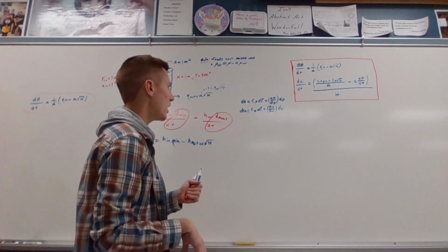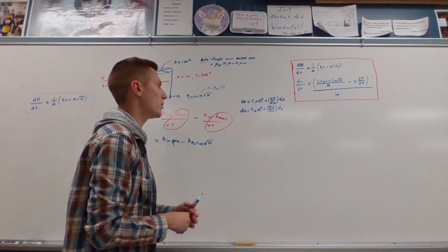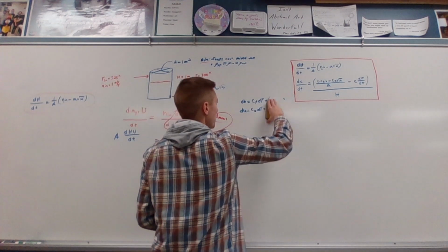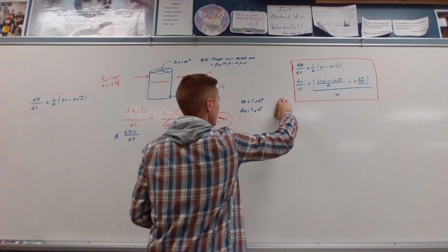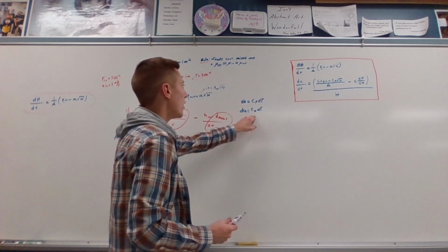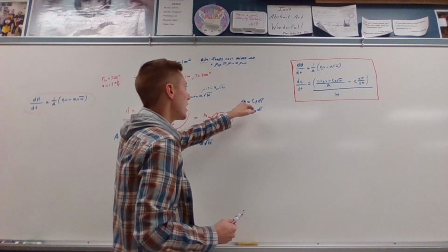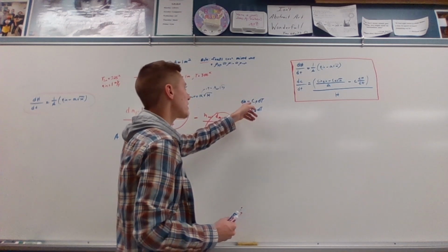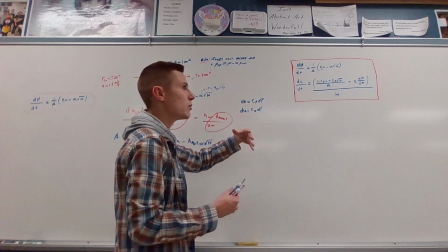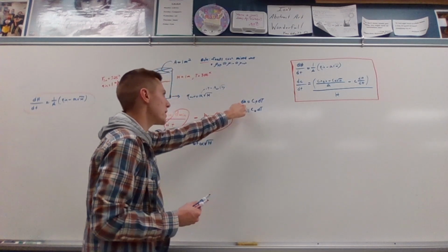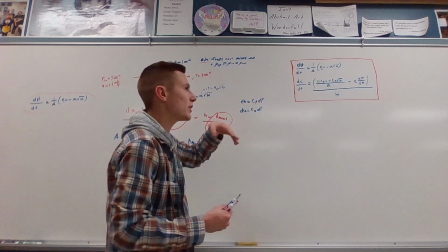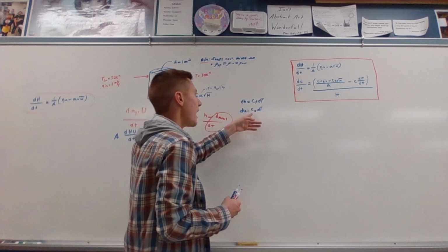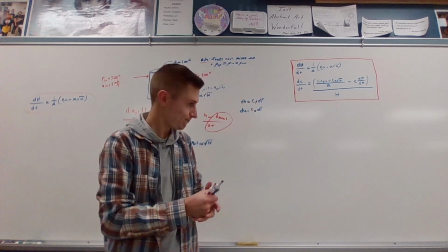For this particular problem we're going to be doing, we want to just ignore our dependent values. So we're just going to go ahead and ignore them. This relationship relates a small change in enthalpy and a small change in internal energy in terms of their heat capacities. For each one of these, our heat capacities are with respect to a different constant. For instance, a small change in enthalpy is equal to a heat capacity held at constant pressure, and for internal energy, it is a heat capacity at constant volume.